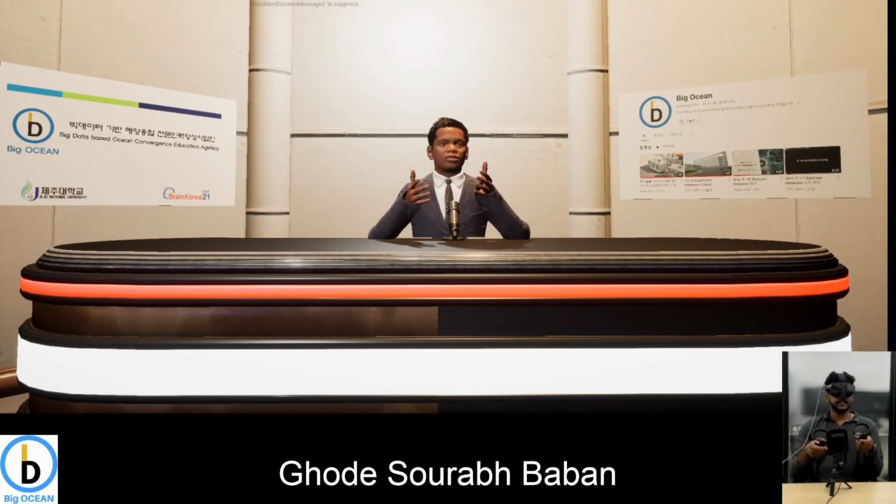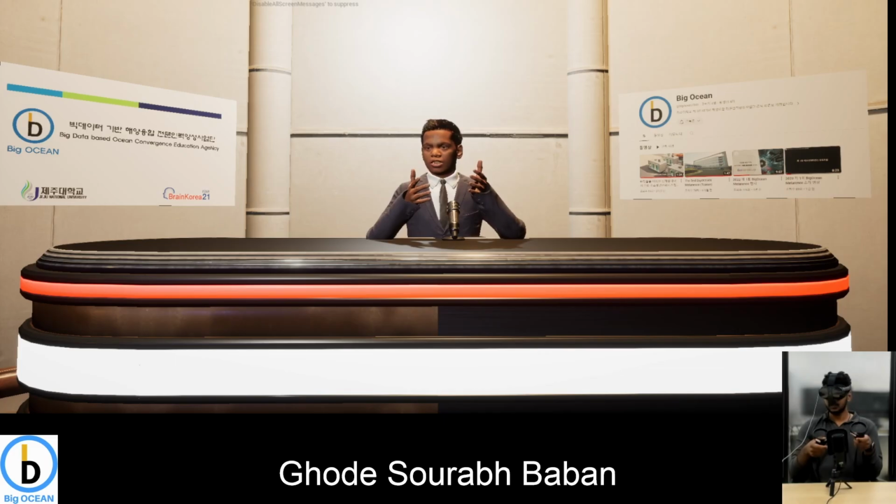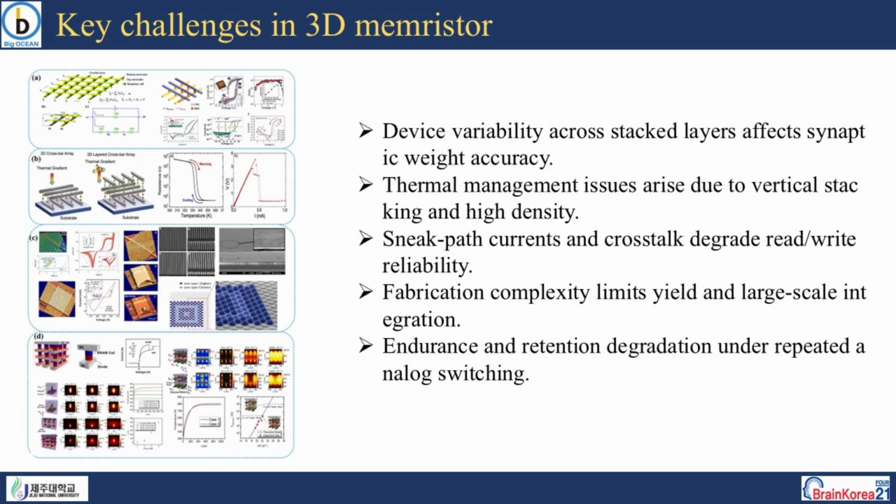But the fabrication of 3D memory has some challenges, like device variability across the stack layers, which affects synaptic weight accuracy. Also, thermal management issues arise due to vertical stacking and high density. Sneak path current is also a big issue: sneak path currents and crosstalk degrade read and write reliability. And fabrication complexity limits yield for large scale integration, along with endurance and retention degradation under repeated analog switching.